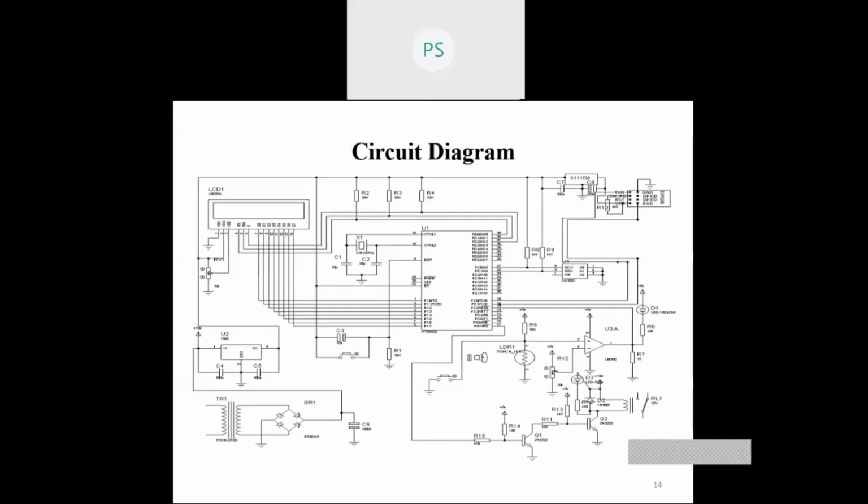When the non-inverting input drops below the threshold value at the inverting input, the output will go low. Otherwise, the output will be in the high state. We have designed the circuit such that when light falls on the LDR, the comparator gives a low pulse to the microcontroller IO pin.